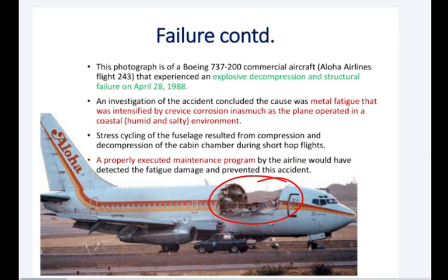But in some scenarios, like where there is fatigue, there is a cyclic load. If you just bend the material in this way and then bend it again, the stress level can be very low compared to the ultimate tensile stress, but the material can fail because of the fatigue. So we will also study this, right?